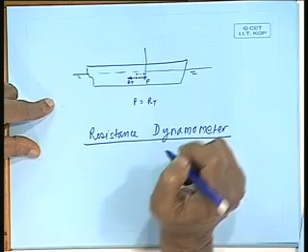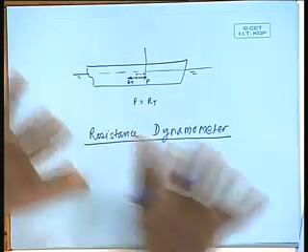The other thing that must be measured is the speed. The carriage is the one that provides the constant speed, which does not vary despite the friction of the rails and all. The carriage is attached to the model by the dynamometer. As for what force the carriage takes, we are not bothered. What force the dynamometer pillar exerts on the model, that we are bothered about.